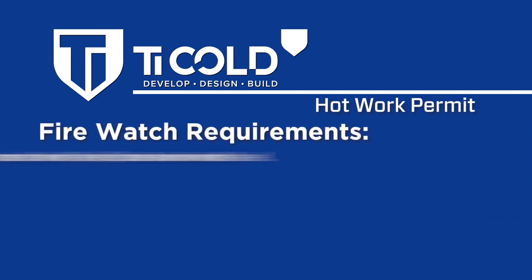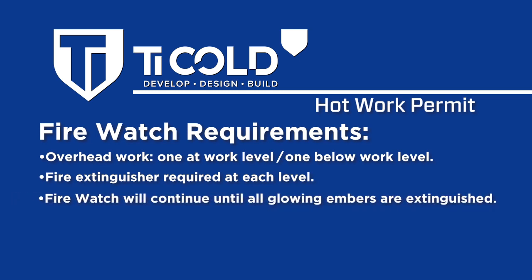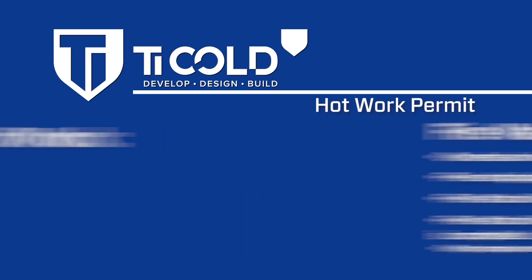Fire watch requirements. Overhead work: 1 at work level, 1 below work level. Fire extinguisher required at each level. Fire watch will continue until all glowing embers are extinguished. Fire watch will continue for a minimum of 30 minutes after work is completed.